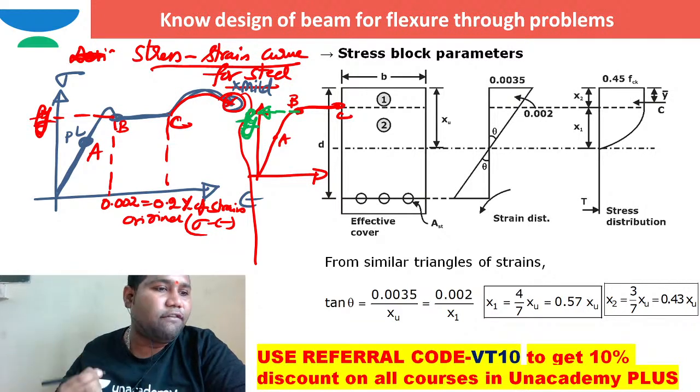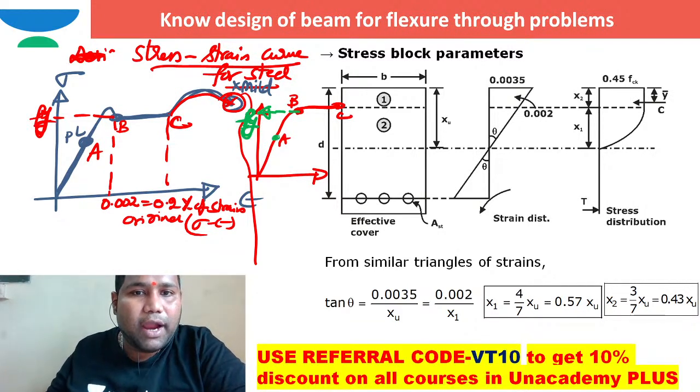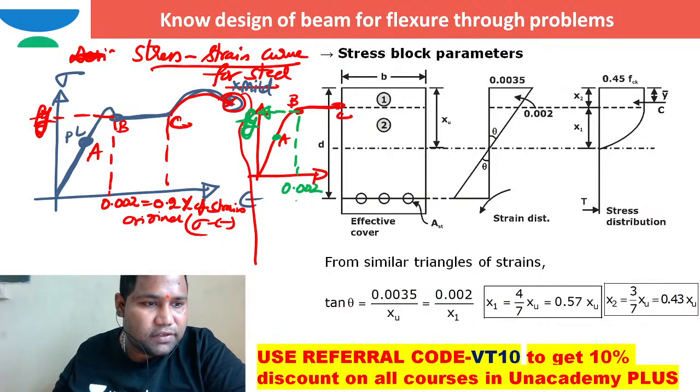We can call it Fy, right? And this point A is nothing but the proportionality limit. Definitely at point B, what is the strain? At point B, the strain is 0.002, which is 0.2 percent strain, right? And at C also the stress is Fy, because BC is there. What is BC? BC is a plastic zone where the stress is constant, only straining is possible, right?